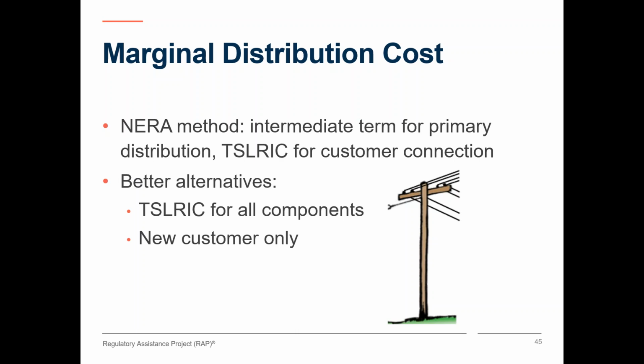I'll focus on one flaw in the NERA methodology for distribution. Because this method uses an intermediate time frame for transmission and sometimes for primary distribution lines, and a new construction method for customer connections, it produces results biased against the residential and small commercial customer classes.